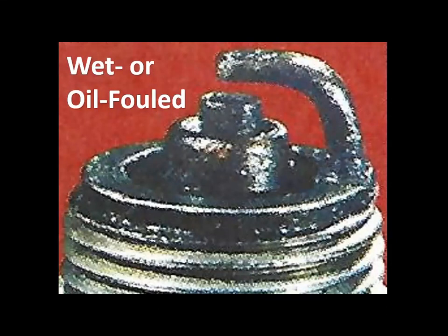Oil-fouled spark plugs are recognized by wet oil deposits on the spark plug insulator and electrodes. Oil-fouled spark plugs have the same effect as carbon-fouled spark plugs. Oil-fouled spark plugs are caused by oil entering the combustion chamber.